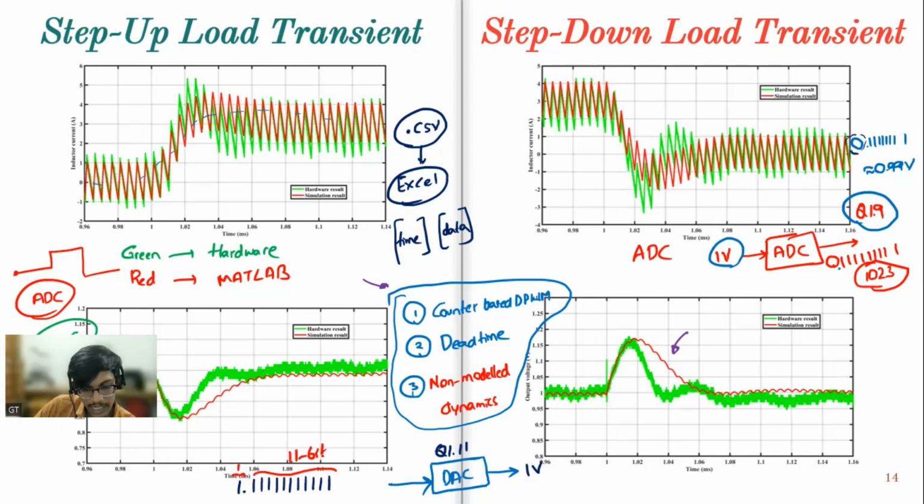So when we are saying digital to analog, it takes in a 12-bit digital number, some number which has no meaning until we give it some value. So we have defined the Q format. Now it will be 2 to the power 0 for the first bit, plus 2 to the power minus 1 plus 2 to the power minus 2 plus up to 2 to the power minus 11, which is almost close to 1 volt.